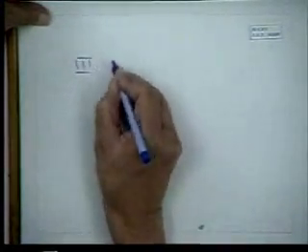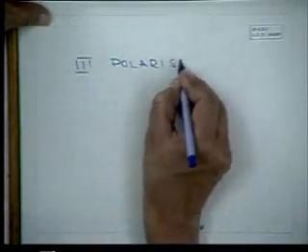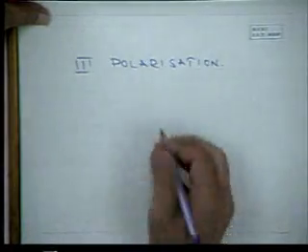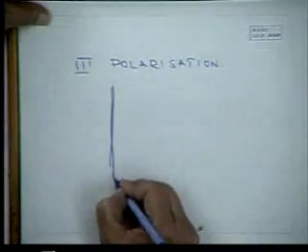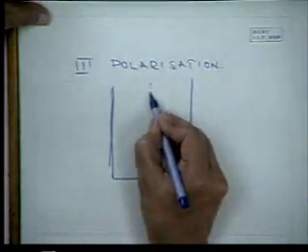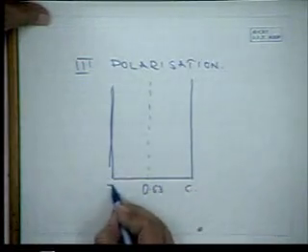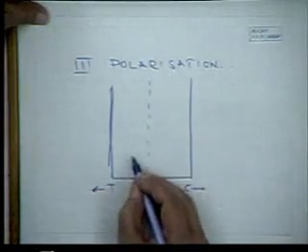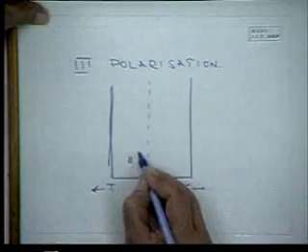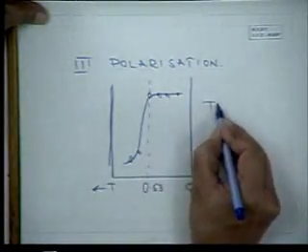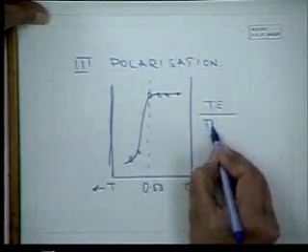That is one, and the band gap increasing also results in a decrease in the Auger process. Okay, so these are two major effects, and I'll just mention there is also an effect on the polarization. Last time I gave a plot something like this. In the InGaAs system for x equal to 0.53, this is compressive and this is tensile. And we showed that the polarization showed a variation something like this, where the polarization was given by the TE component over TE plus TM.